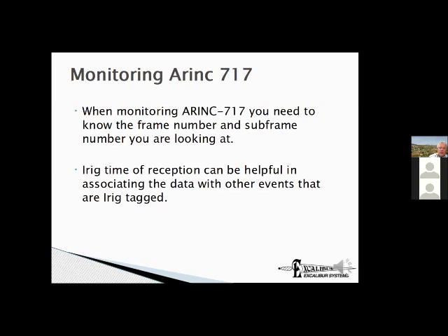You can also use an ARINC timestamp on words. In that case, you not only know what time it came in, but you also know relative to other things on the aircraft who might have also used ARINC, because they all get the same ARINC value. Now, ARINC basically puts out a mark once per second with extreme accuracy, but only once per second.